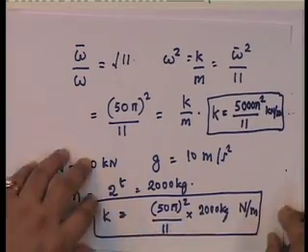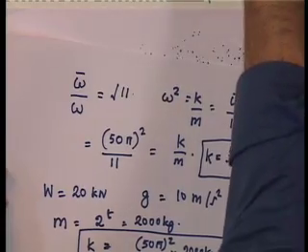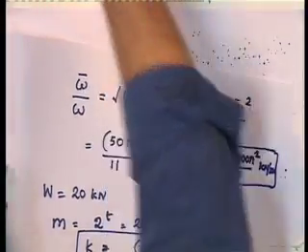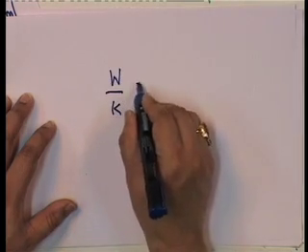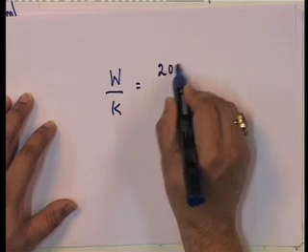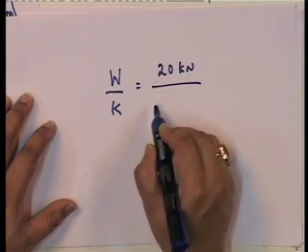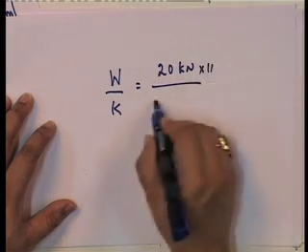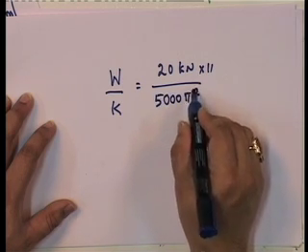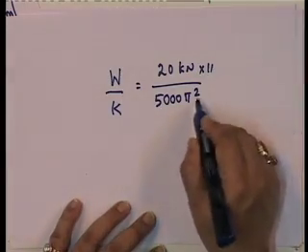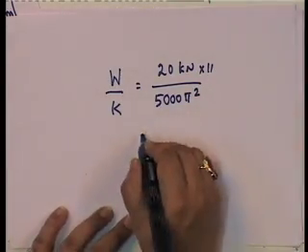So, let us now look at under the weight what kind of displacement do I get? I mean, what kind of travel do I minimum require? The minimum travel required is weight upon k. So, that is equal to 20 kilonewtons divided by, so into 11 into 5000 pi squared. Pi squared is approximately about 10, I can take it as 10 for this particular purpose.